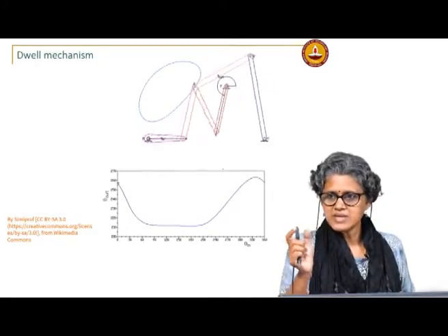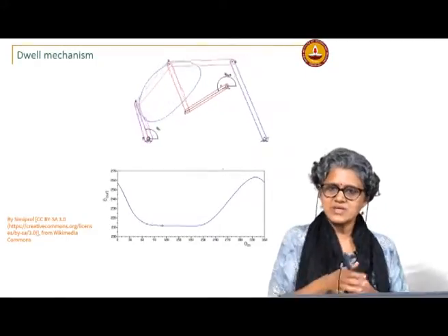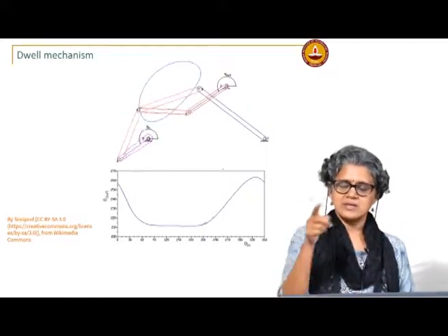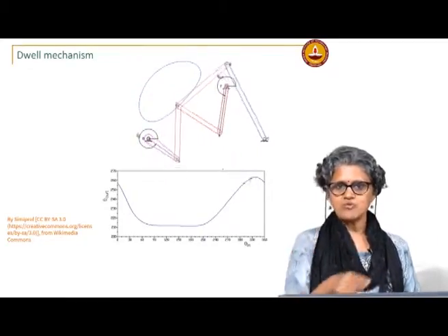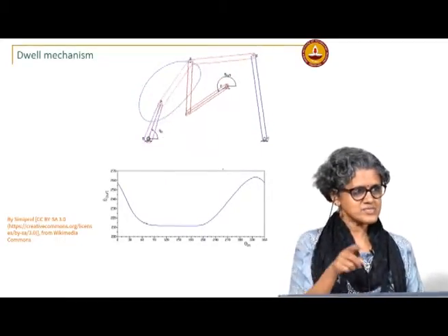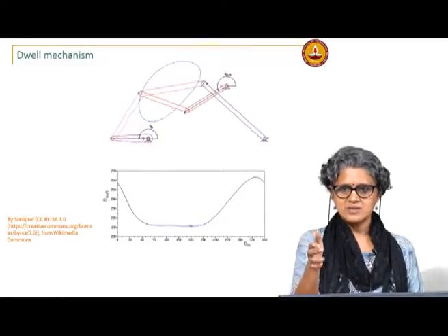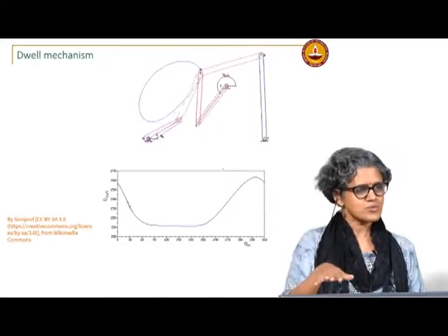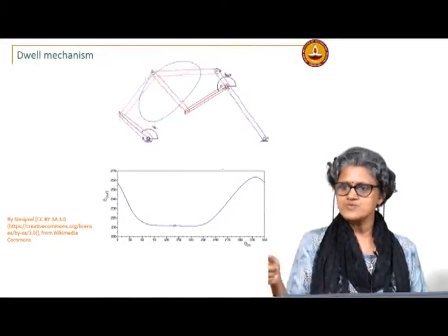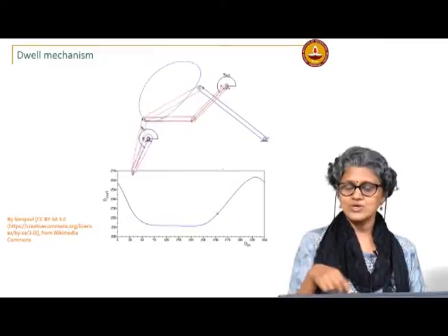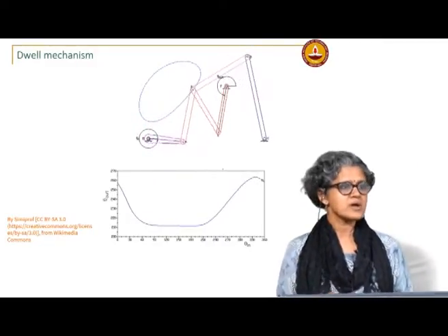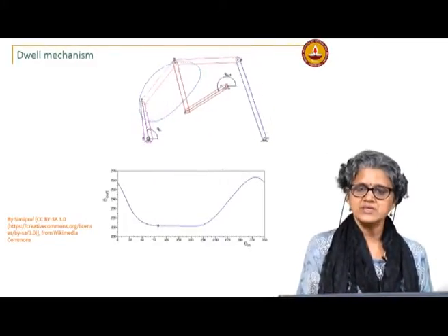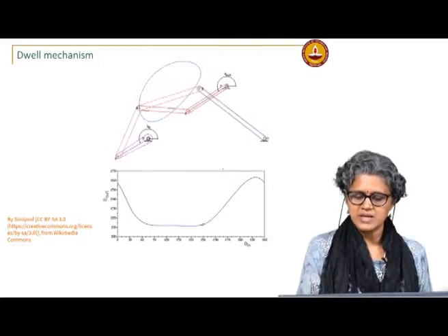Okay, the dwell in the mechanism gives you the time. So, the boxes are continuously moving. You have a continuous input, the box comes at an instant where there is a dwell in the mechanism, you put the label onto it, then it moves away, and so it is very useful for those sort of applications in the assembly line.